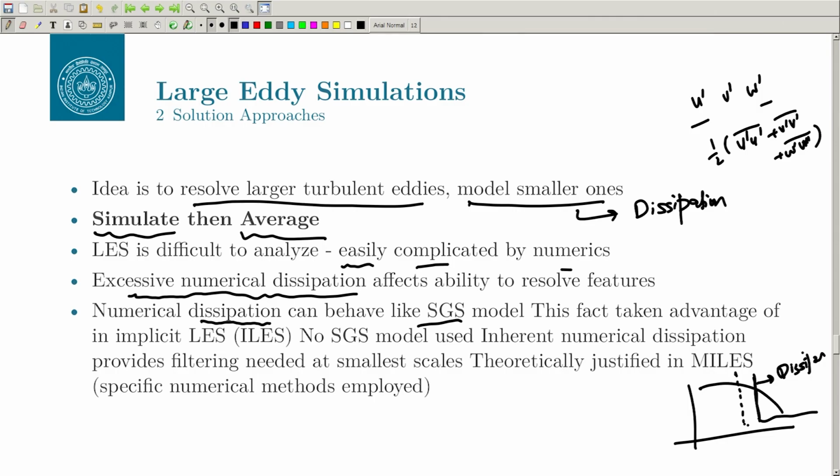So, there are these two different schools, and without going into that, in the literature you will find all kinds of simulations in LES. And as I discussed in the beginning, there are different ways of doing LES. So, they have WM LES, which is wall model LES, and there is very large LES, VLES, and then there is some hybrid model. WM LES is also a kind of hybrid model. There is WR LES, which is wall resolved LES.